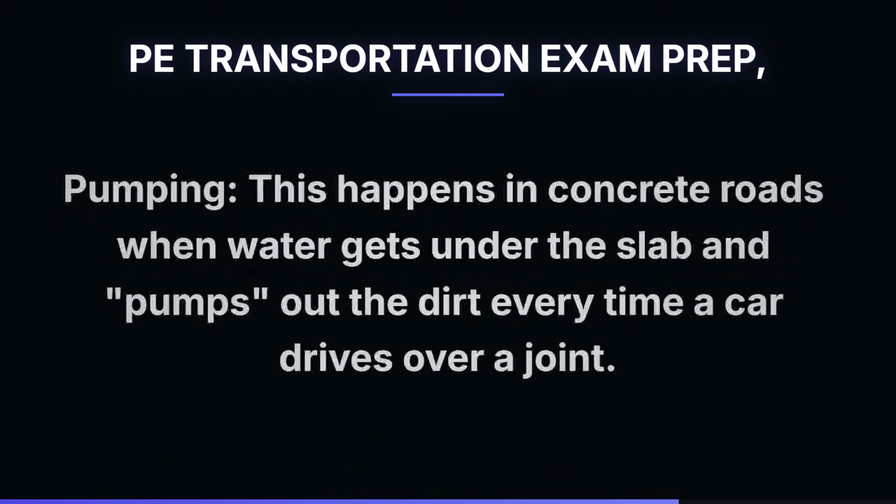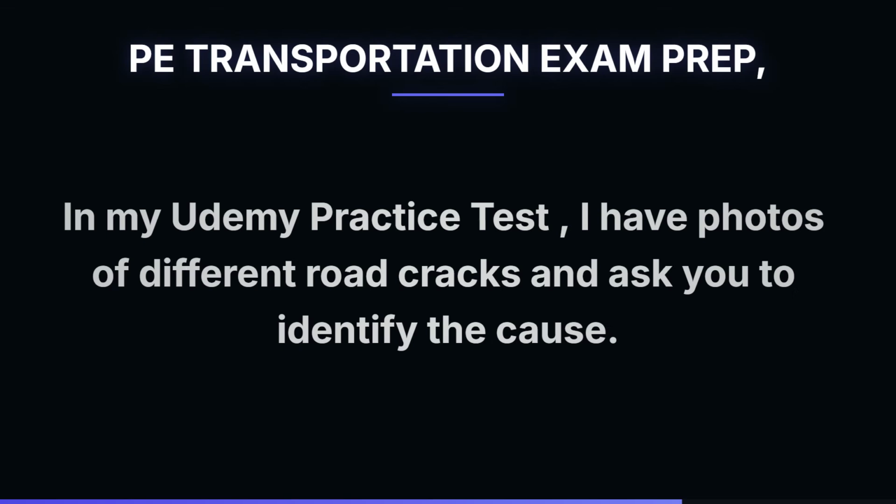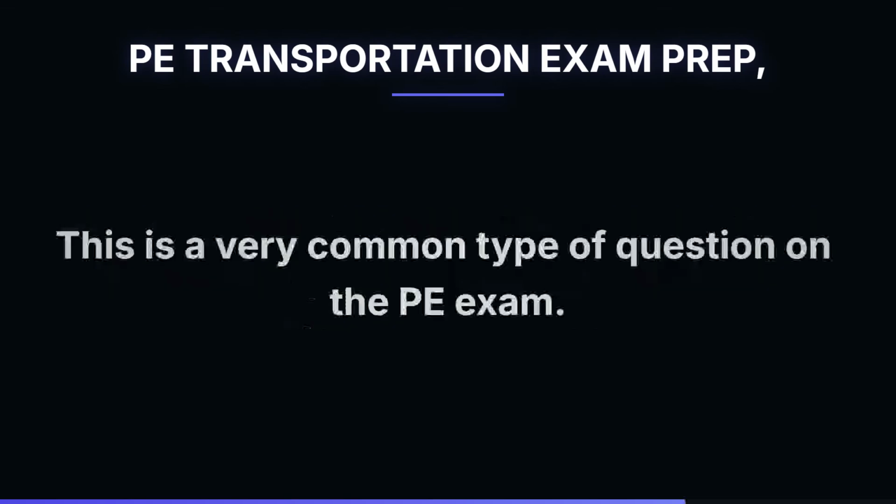Pumping. This happens in concrete roads when water gets under the slab and pumps out the dirt every time a car drives over a joint. In my Udemy practice test, I have photos of different road cracks and ask you to identify the cause. This is a very common type of question on the PE exam.